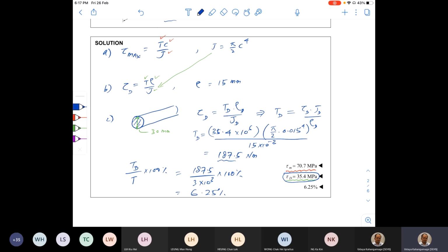Most transmission shafts are also hollow, for the same reason, because the middle contributes only a little bit to supporting the load. Therefore, there's no point in having the material in the middle. Okay, so that is why most of the time we use hollow circular shafts. Right. So I think it's very good because we learned something new from this question.